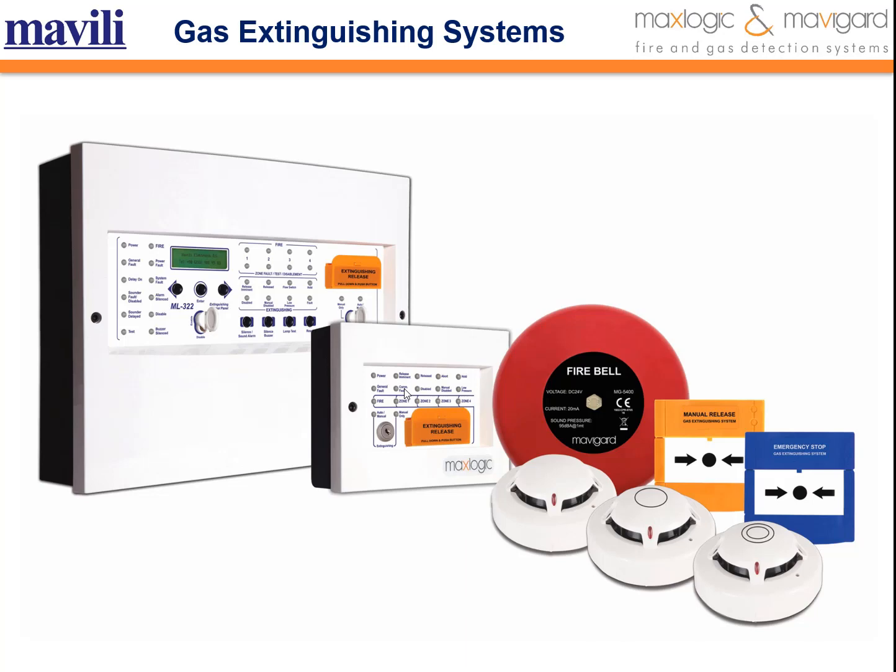There are 4 inputs in the status indicator unit. These inputs are standby, cancel, extinguishing status switch, and remote reset inputs. Open circuit and short circuit conditions of the inputs are controlled by the display unit. In case of any error, the fault information is sent to the fire extinguishing panel.